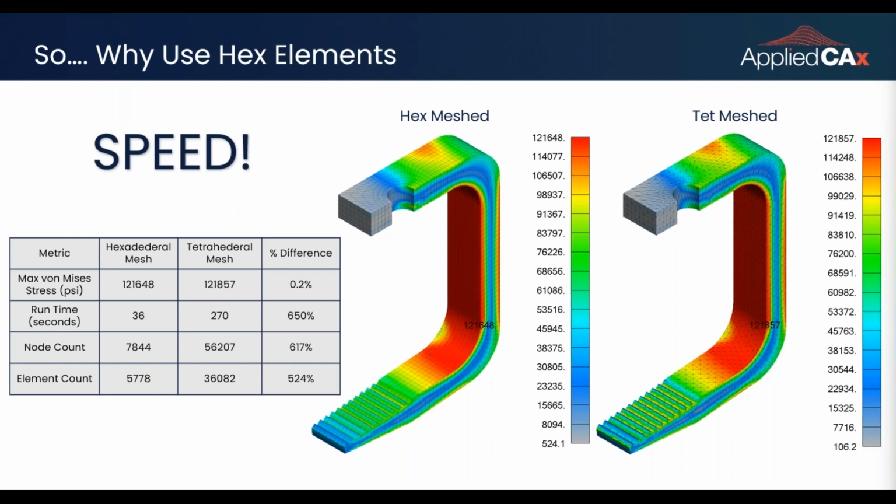Right on. So we have a couple of questions. The one I thought was probably on a lot of people's minds is, what about the 3D hybrid meshing? So the most recent versions of Femap have come out with an auto hex mesher, which does not require your geometry to follow all the rules of a clean base and top connected by four-sided surfaces on the edges.